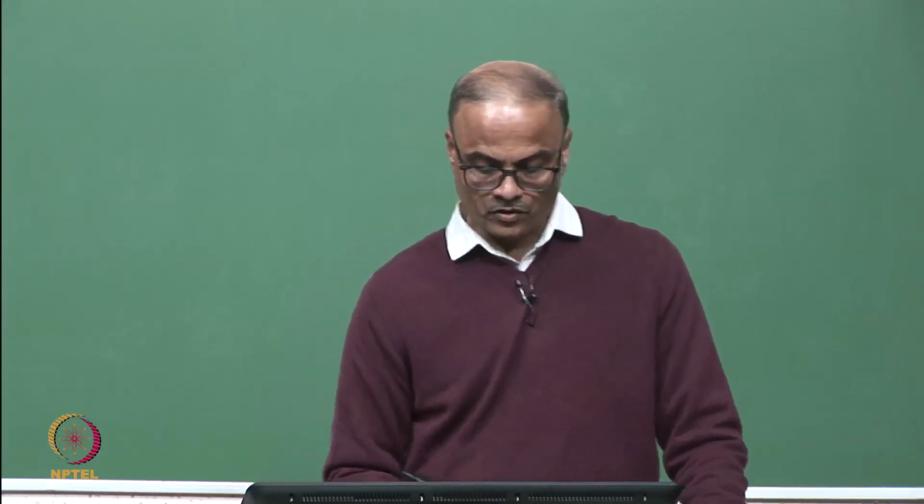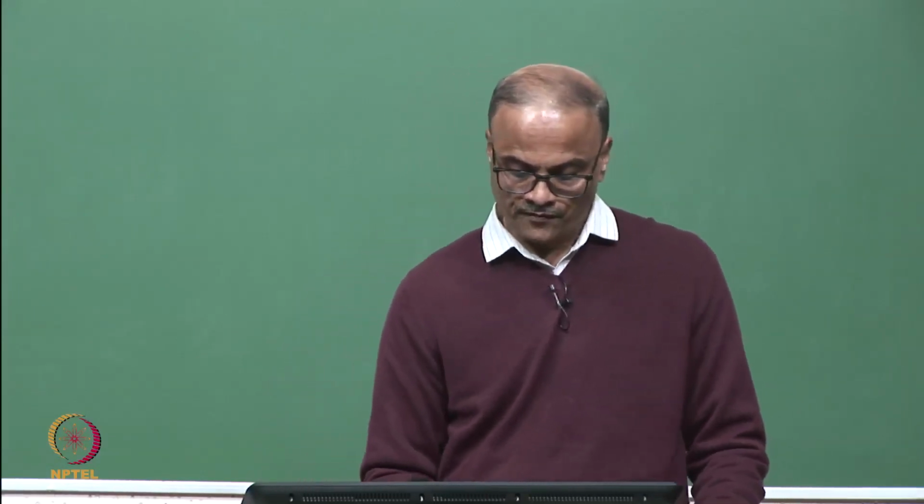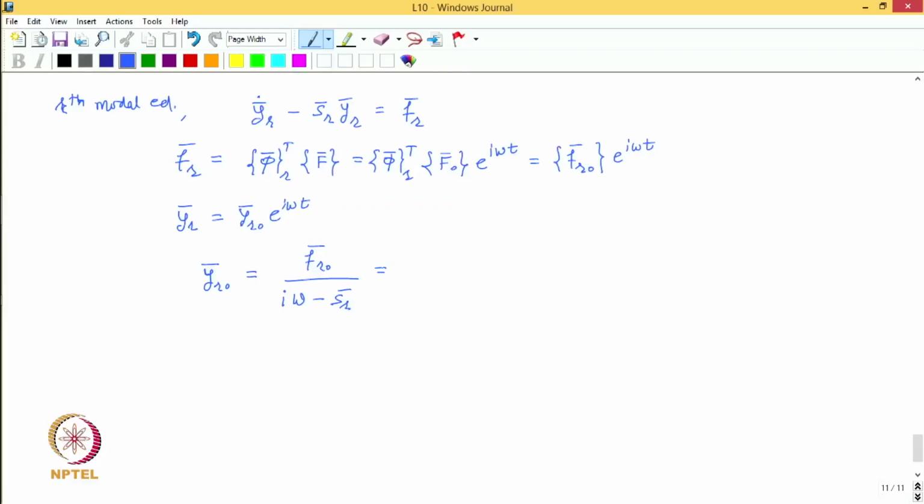Now, if we substitute F r o bar, which is equal to phi bar r transpose F bar o, then we get this expression, which is nothing but the amplitude of modal response in state space.